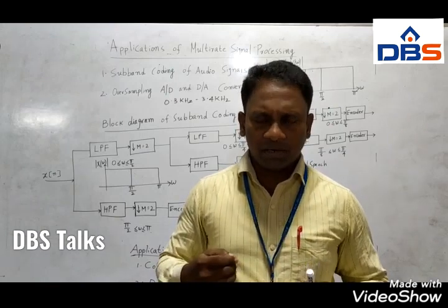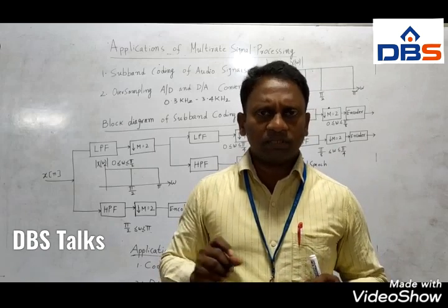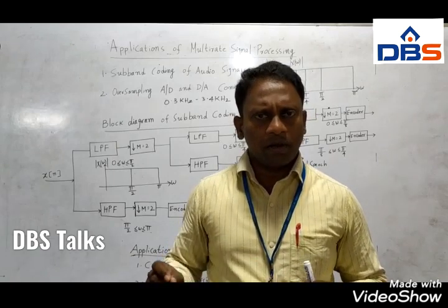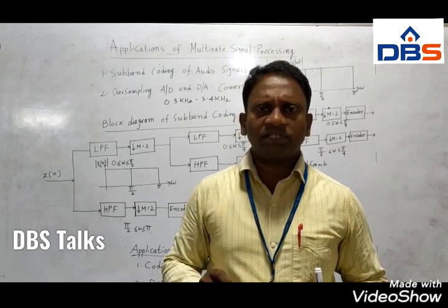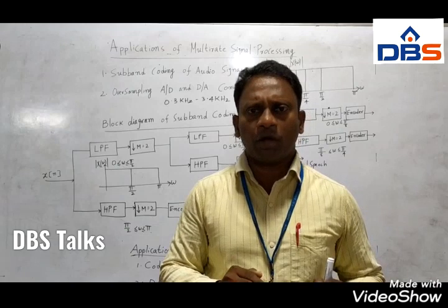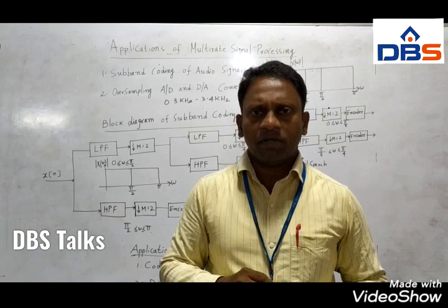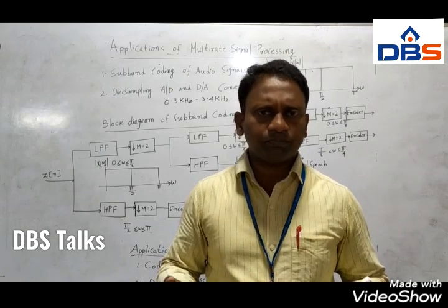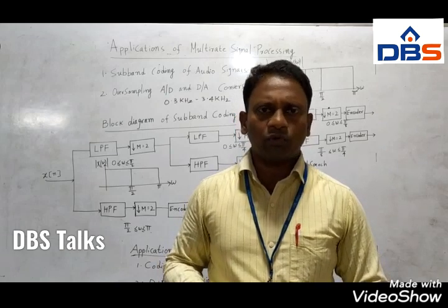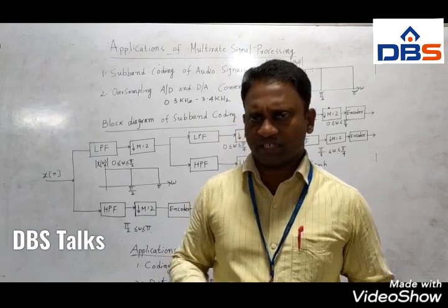If you code the voice signal with the same number of bits, then every energy component or every frequency component is uniformly treated and represented with a uniform number of bits, so you may lose some quality of the signal. To improve the quality of the signal, we have to code it separately at low and high frequencies.